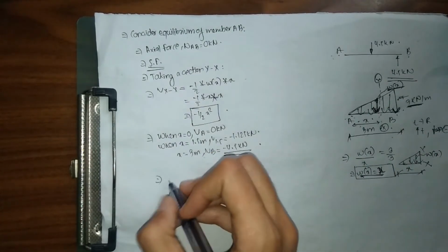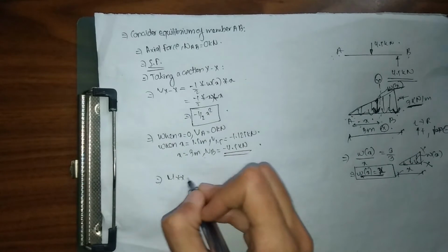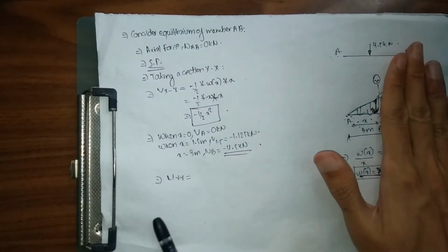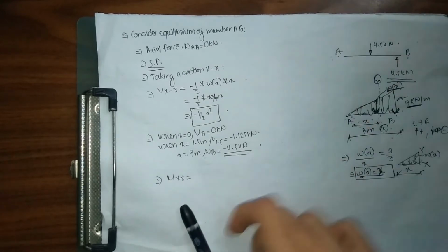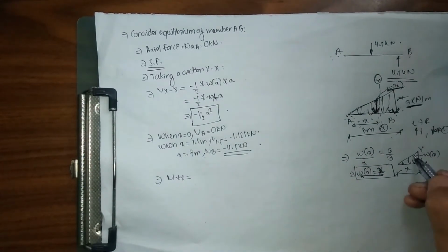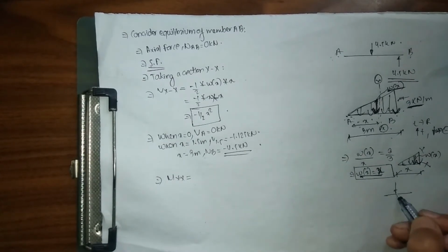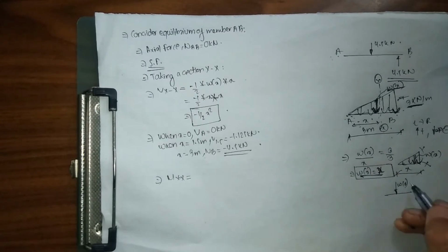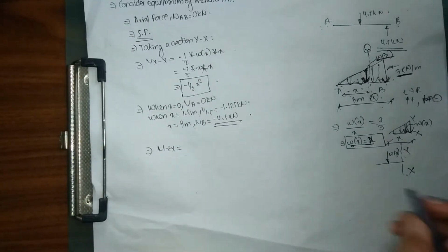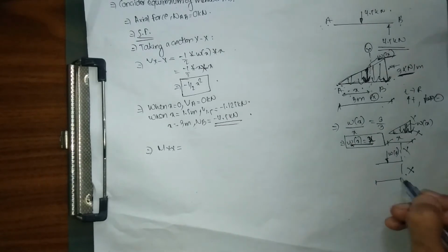So my bending moment Mxx is simply going to be equal to, so right now I am moving from left to right. Do not see the section behind xx, so just see the section before xx. I have my Wx, I have my UVL of Wx. Let me see this figure. UVL of Wx acting downward. So if I convert it into point load, this is my Wx, and this is my shortened section xx. So let me explain in this way. This is my shortened section xx, and the total distance is x.